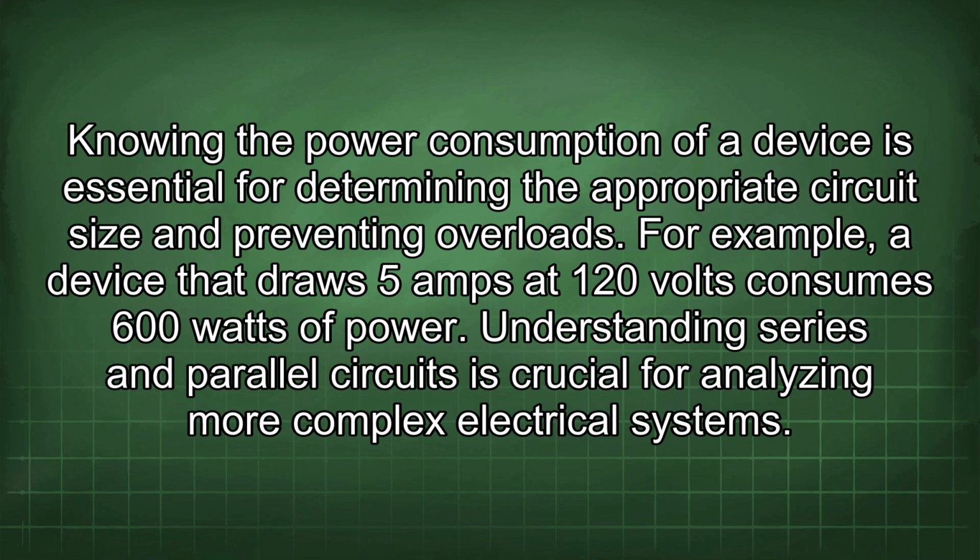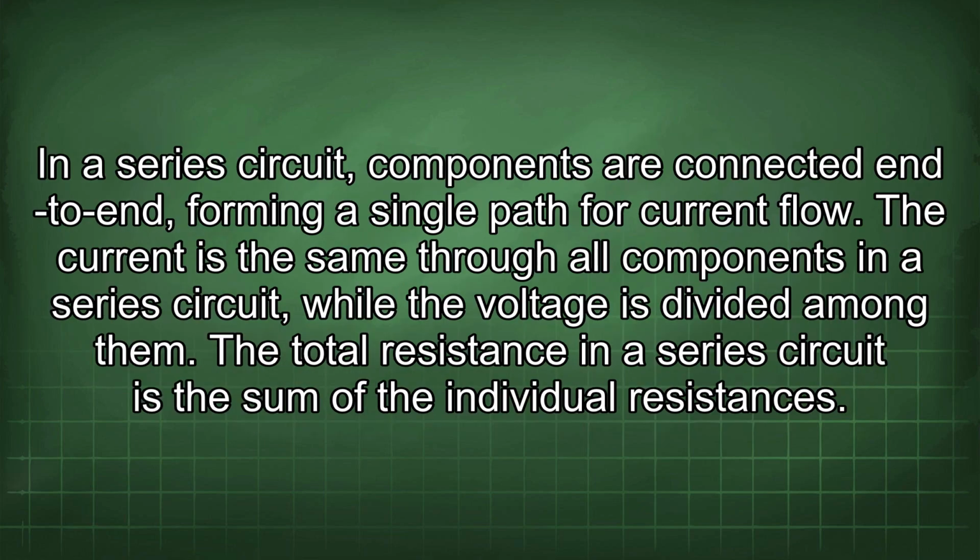Understanding series and parallel circuits is crucial for analyzing more complex electrical systems. In a series circuit, components are connected end to end, forming a single path for current flow. The current is the same through all components in a series circuit, while the voltage is divided among them. The total resistance in a series circuit is the sum of the individual resistances.